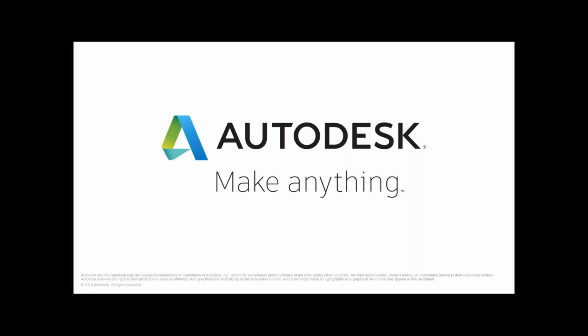So the gentleman, Raymond, you've got a question around the object enablers not coming in Plant 3D. Usually that's associated with the installation order, so try repairing that. You can always just install the object enablers again, and it should work. But if that doesn't help, please raise a case.